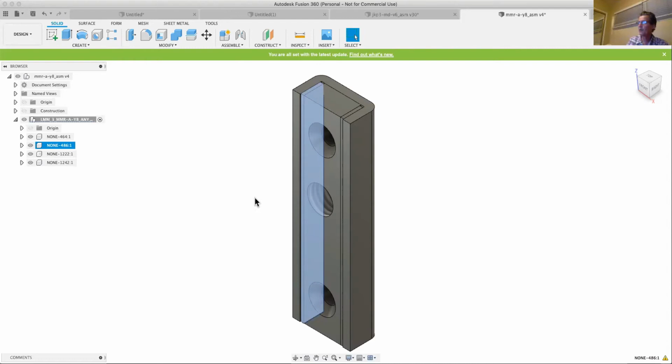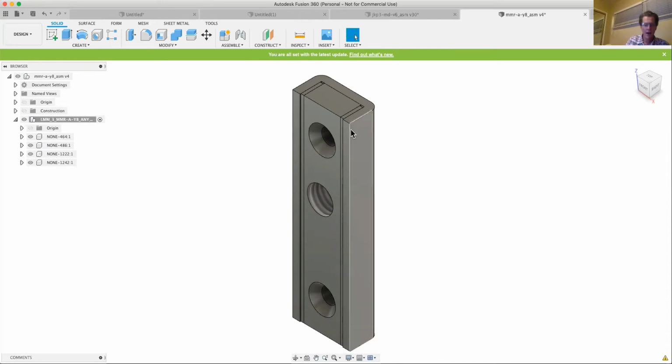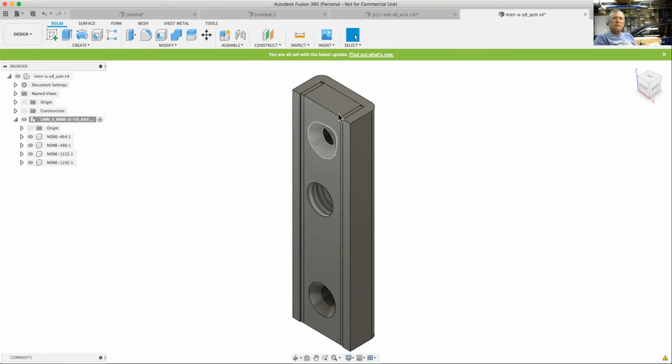That's a good point, because historically there's problems with it. I haven't run into problems with step files importing into Fusion 360 or pretty much any other package. The step file translation seems to be quite solid. IGES files, I've run into odd things, a little bit like you sometimes run into with STL files where a seam is open and the mesh isn't properly closed. But step file actually uses a solid part definition. And I have not seen a lot of trouble.